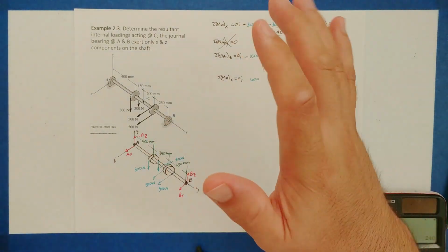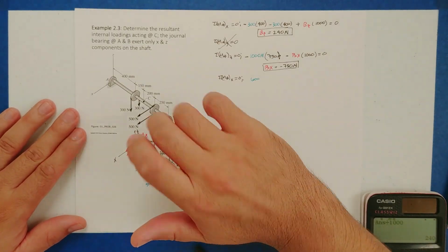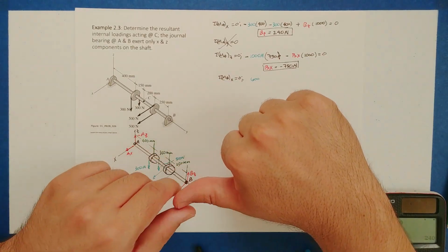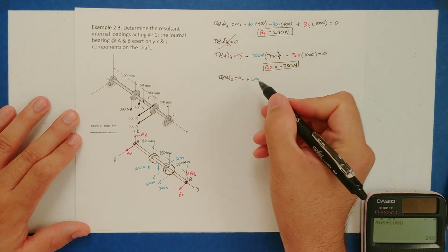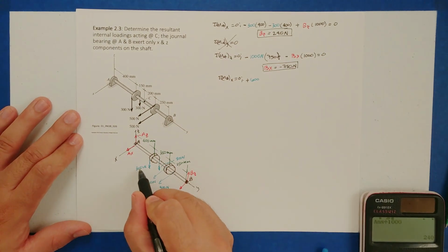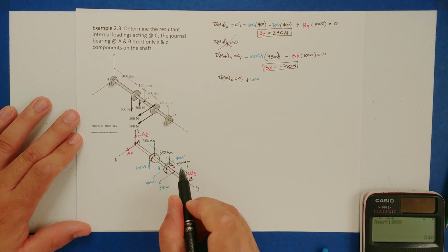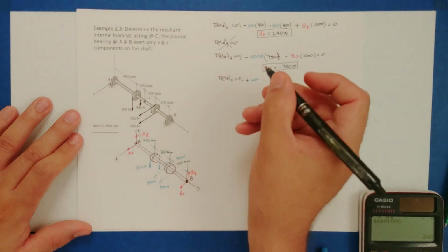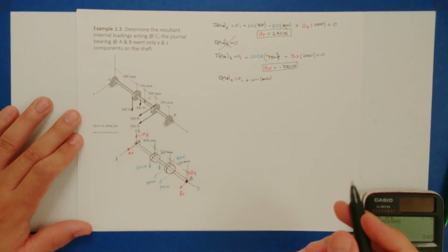With the right hand, make sure you're using the right hand here, that would be a rotation like so. Notice that twisting puts my thumb pointing towards the right, so this is a positive moment. The force is 600, since 300 plus 300 is 600. And the distance to point B is 350 plus 250, which is 600, I believe. 3 plus 2 is 5, and 50, yes.